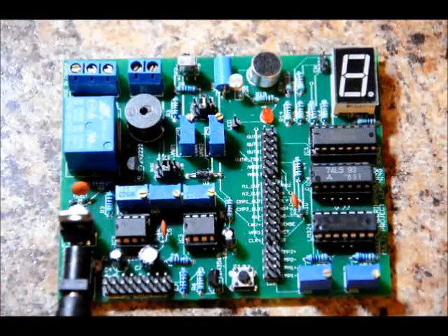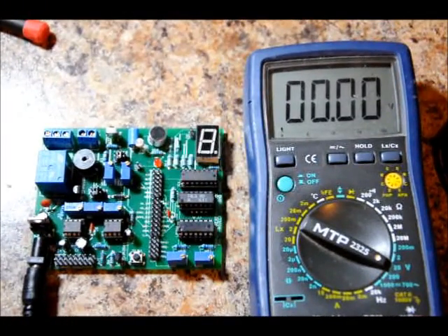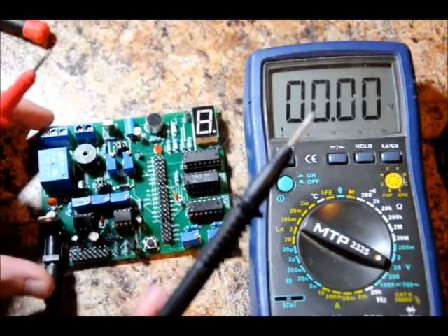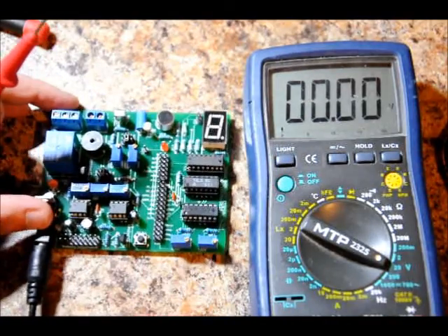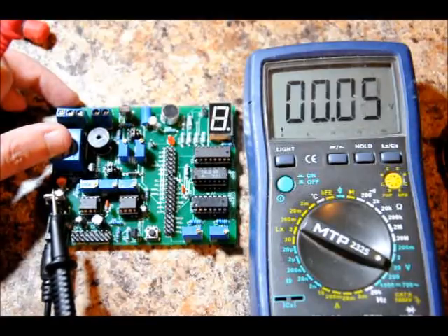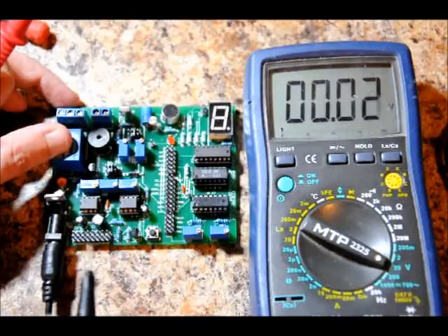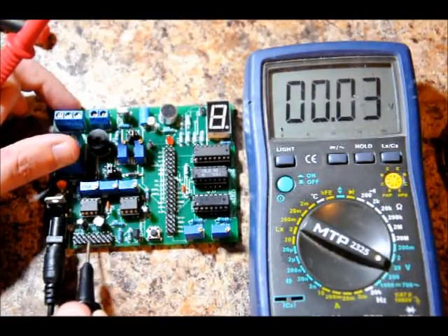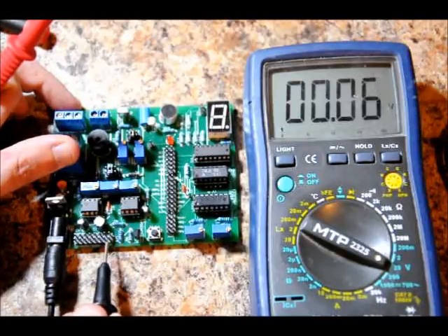So what I need to do is bring in my multimeter. Now I've got my multimeter set to read voltage, so I need to put my negative probe on the ground line of the board. Now I can do that one of different ways. The 7805, again tutorial below on what the 7805 does, regulates to 5 volts. The top pin is actually ground. Or I can use any of the ground lines here. All of the bottom row here is labeled common for common ground.